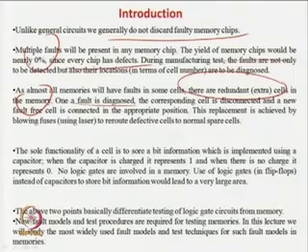So, this is from memory repair, we are not going into details, but the idea you have to understand is there is some kind of repairing available. So, there are some 10 cells which are damaged, so there is a multiplexing arrangement, in which you can connect the inputs which are going into the damaged cells to the extra redundant good cells. Similarly, the output of the failed cells should be cut off by using a multiplexing arrangement, so that the output of the good redundant cells in your chips can be brought into the normal memory area. So, by using some multiplexing, once a fault is diagnosed, the corresponding cell is disconnected and a new fault-free cell is connected in the appropriate position.